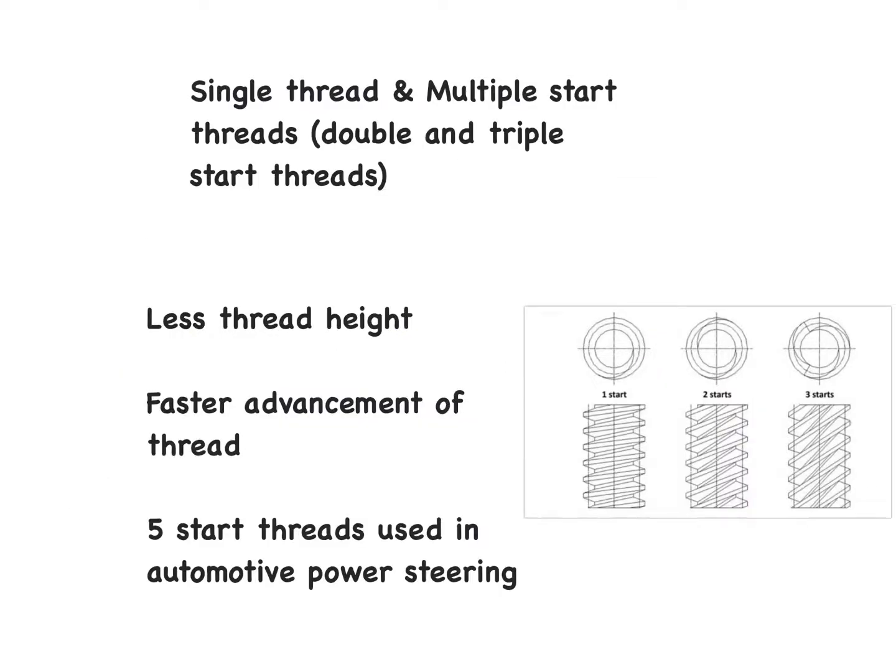A little while ago, I talked about the lead and its relation to the pitch. Now I'm talking about multiple start threads, double start threads, triple start threads, or single start threads. So I have shown here three diagrams. The difference is it's as good as thinking like you have two strings attached to a pencil that are running parallel to each other. So here also, when you have multiple start threads, there will be multiple threads which will run parallel across the shank.